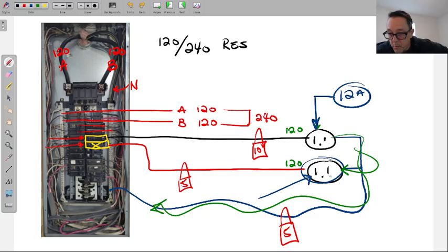If you go to now remove this outlet, you take off this hot conductor, you shut off the hot, this neutral is live right now. It has 12 amps on it, has 120 pushing it, and if you ground yourself in this system, now it's going through you to ground. The neutral is the most dangerous conductor in the circuit because it has that load current on it, which can be accumulated from having shared the neutral in different circuits.